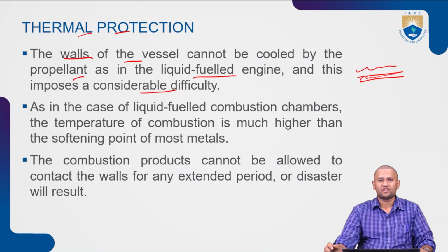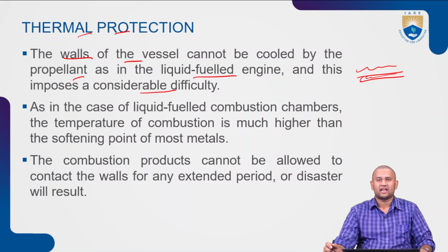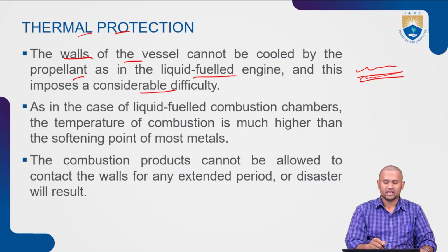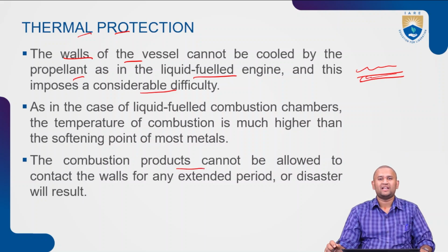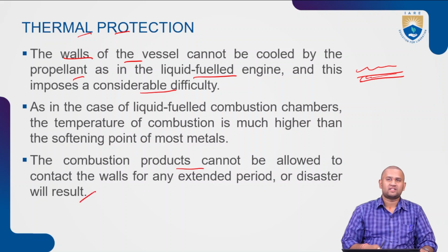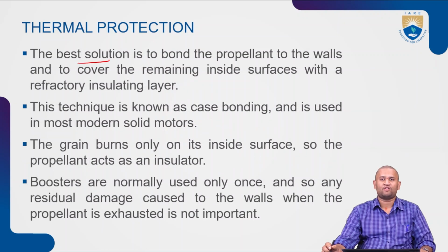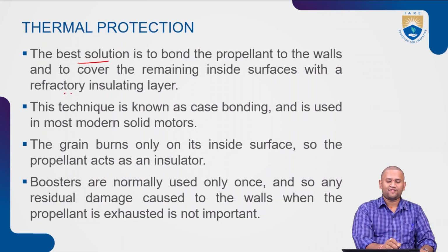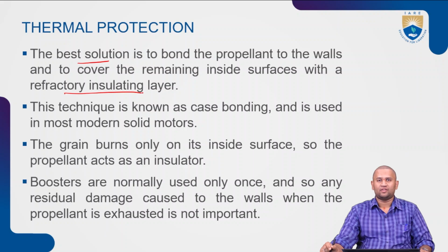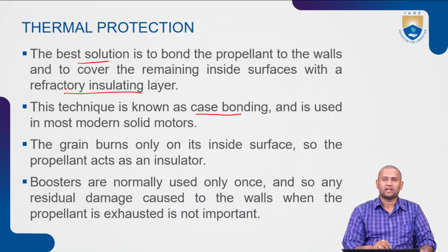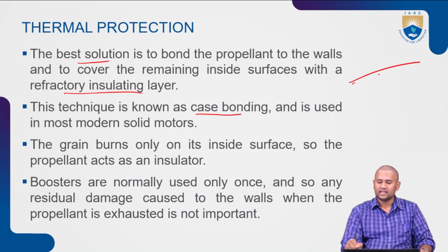As in the case of liquid fueled combustion chambers, the temperature of combustion is much higher than the softening point of most metals, and the combustion products cannot be allowed to be in contact with the walls for any extended period, or disaster will result. The best solution is to bond the propellant to the walls and to cover the remaining inside surfaces with a refractory insulating layer. Now, this type of technique is called case bonding, because onto the case we are creating a